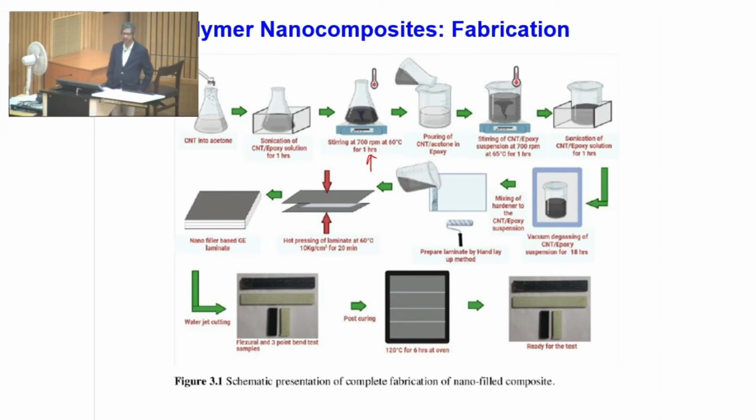However, agglomeration of nanoparticles is a big problem in all these things. Hence, several investigations have shown that a small level of agglomeration can decrease the strength to failure by several tens of percentage. An additional mechanism that occurs for well dispersed nanoparticles which are weakly bonded to the matrix is the phenomenon of cavitation. Okay. In other words, nanoparticles can act as voids actually. They can create voids which initiate the yielding and increase the volume of material going through the deformations.